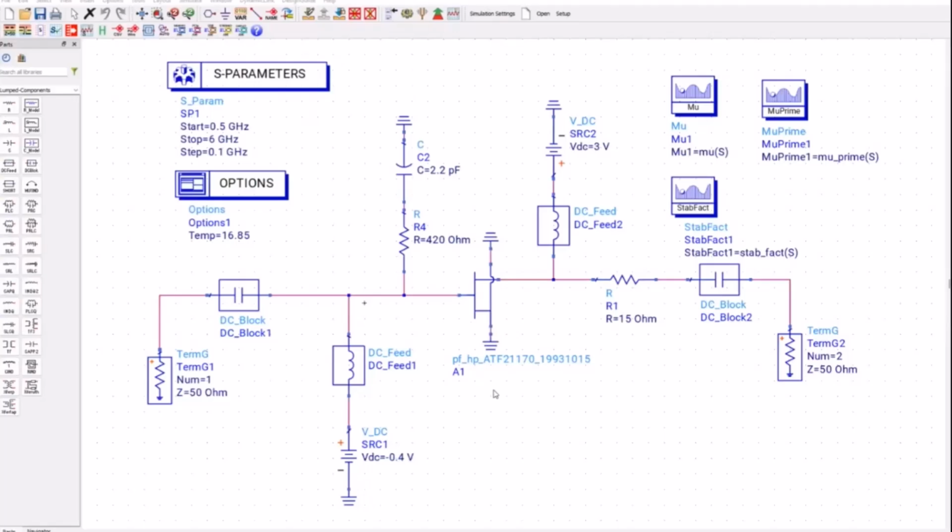degeneration. In PCB, never put anything to the source or the emitter of the device. If you're using BJT, it's the emitter. If you're using FET, it's the source. Never put anything there. Don't use any negative feedback loop or anything, because at low frequency your device might get destabilized, but this negative feedback loop or inductor which you put here will kill you at high frequency. This will give you a lot of stability problems at high frequency.